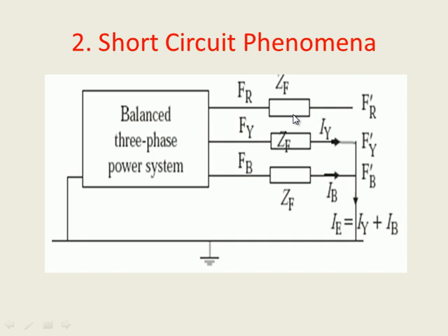Now, if we are going to talk about the surges, the speed of these surges is determined by the time constant of the generator windings, which vary from a few cycles of the 50 Hz wave for the damper windings to around 4 seconds for the field windings. Obviously there is a time constant, that is why these transients will be sufficiently slower than the surge phenomena, because time constants of transformers and generators are being added to this. That's why they are in the second category.